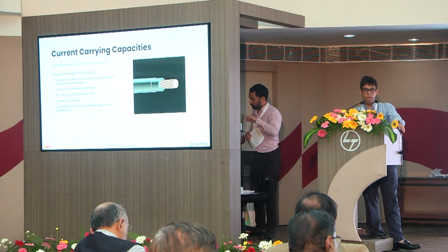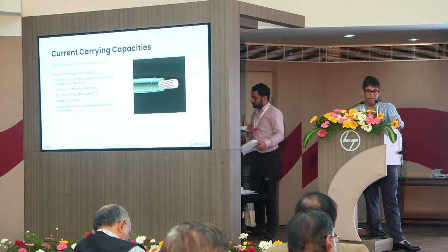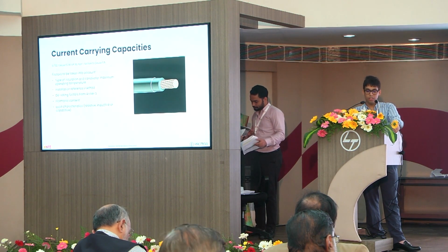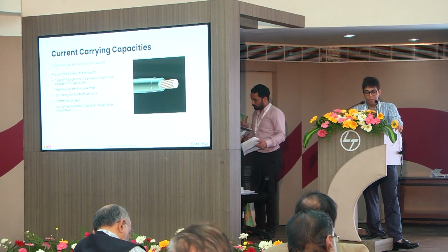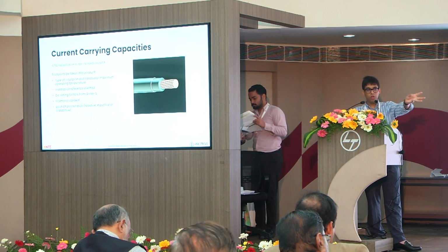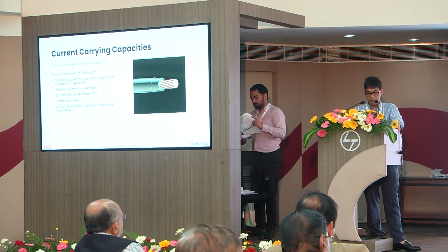Also, you have to look at harmonic content. Like I said, a 4-core cable is only rated for 3 loaded cores. Any more loaded cores, and then you will need to derate. And whether the loads are resistive, inductive, or capacitive will have some effect. Obviously, when your 3 phases combine in the neutral, this is out of the scope of 732, but just keep this in mind.